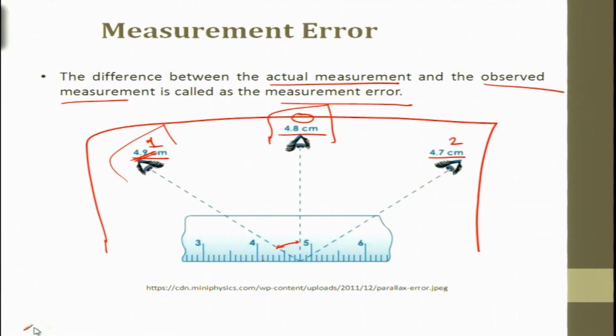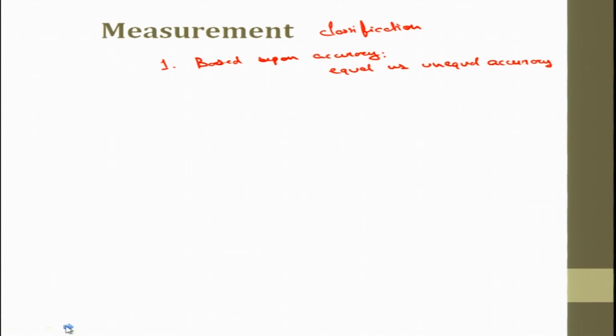Sometimes at different conditions, the measurement values have different accuracies. So the methods used for reduction of measurement of equal accuracy and measurement of unequal accuracy are slightly different. Thus, prior to reducing a series of measurements, a check needs to be performed to determine whether or not measurements are of equal accuracy. So this is generally done using the F-test or goodness of fit test, chi-square test that we might discuss.